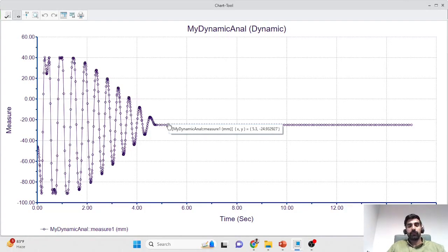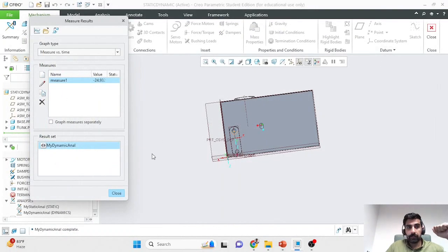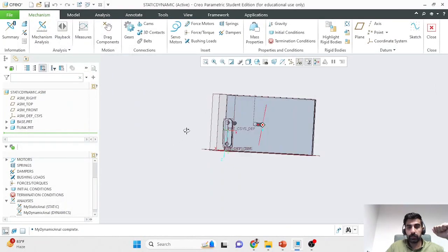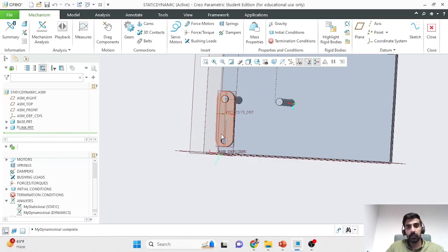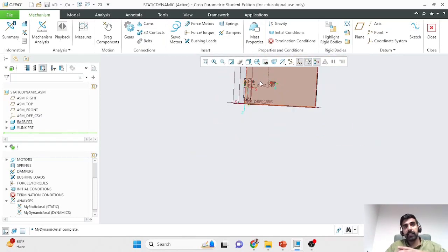Play around with the different values of friction. If you increase friction, what should happen? You would expect that things would come to a halt quicker because you're dissipating energy faster, but explore that on your own. And you have an assignment associated with this topic in which you have to add a second linkage to the end of this pendulum and then repeat this exercise. And you should use the same link that you make for a second time in assembly. Pull the whole thing up, drop it, and set up your dynamic analysis such that your assembly eventually comes to a halt. So set up friction parameters accordingly. They should be realistic as well for the materials that you've selected, and set up your duration of analysis accordingly.